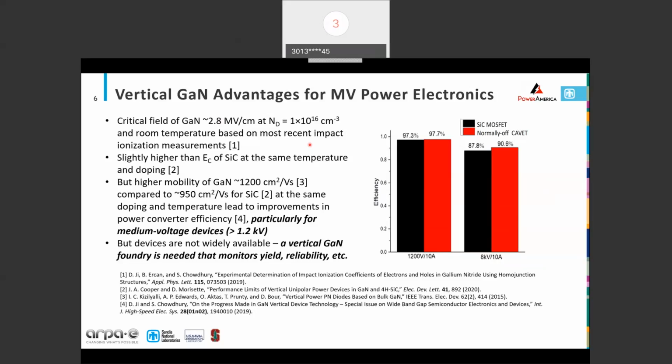In terms of a PN junction versus a JBS, say, of course, you don't want to have that 3 or 3.5 volt turn-on associated with the PN junction, right? Because that's a significant loss mechanism. So that's why us and other folks are trying to think about JBS diodes and so forth.